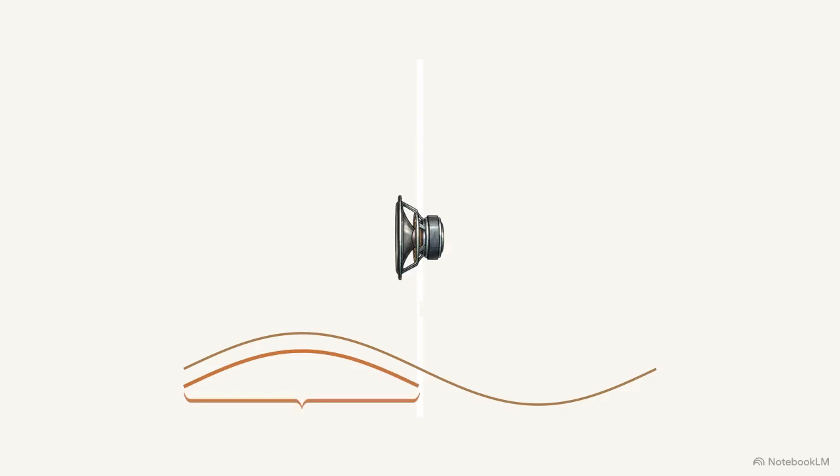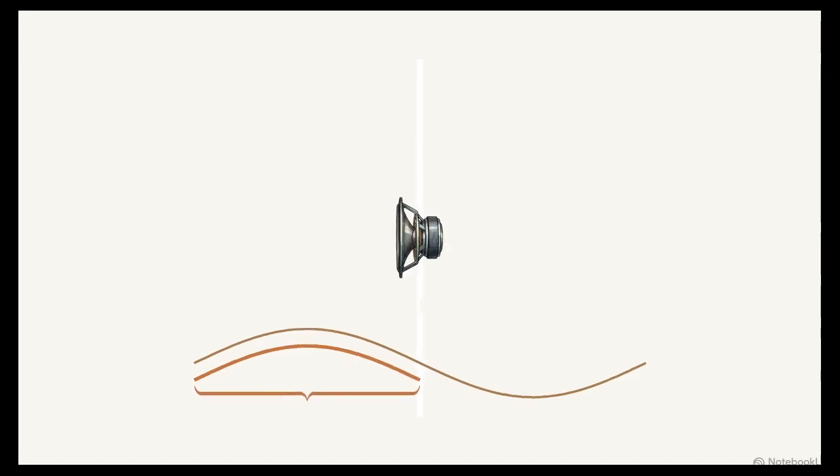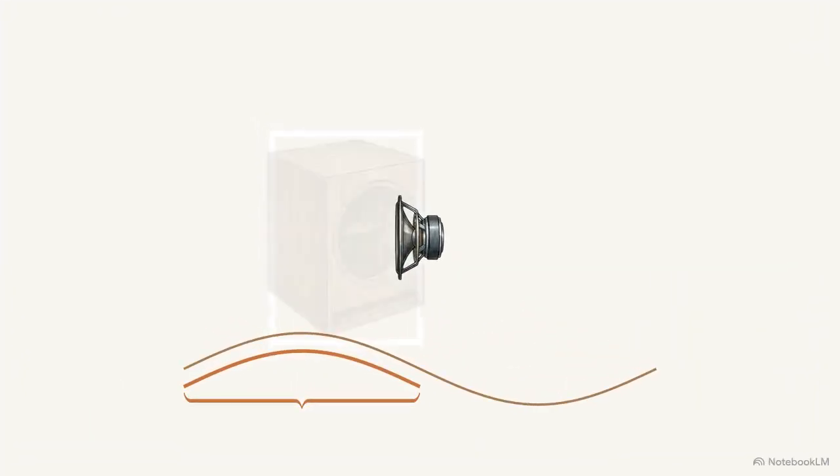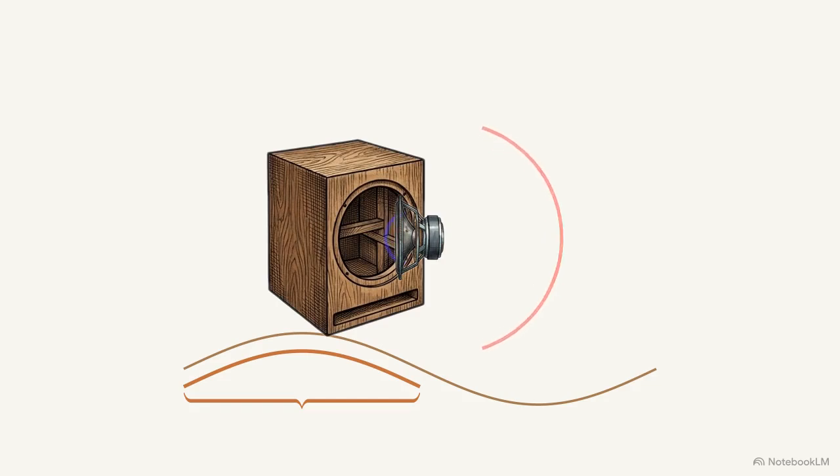The simplest acoustic fix is to mount the speaker in a flat baffle board, serving as a physical barrier to separate the front and rear waves. To be effective, the shortest dimension of this board must be half the physical wavelength of the lowest note it intends to produce. A 40 Hz tone has a wavelength of approximately 8.5 meters. Half of that wavelength means a flat baffle would need to be 14 feet square just to block the wave cancellation. Folding that baffle back on itself creates the compact, six-sided box used in modern systems.